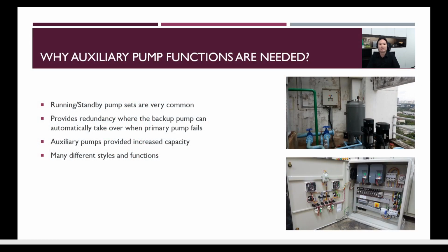Why are the auxiliary pump functions needed? Basically, in a lot of systems, we have running and standby pump sets, which are very common in Malaysia, and I believe everywhere else. It provides redundancy where the backup pump can automatically take over when the primary pump fails, because no one likes to be in the situation where the taps run dry. The auxiliary pumps also provide increased capacity. When the demand is too high for one single pump, the auxiliary pump can kick in and provide the additional flow required.